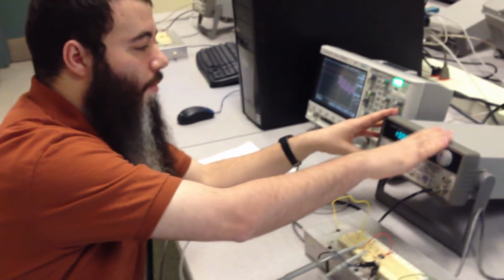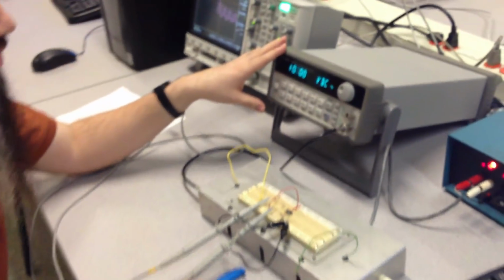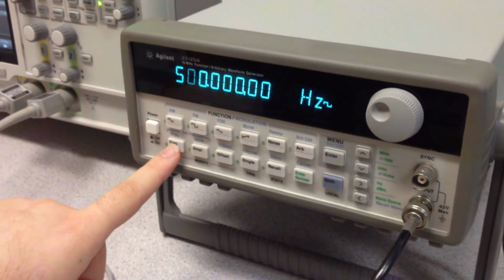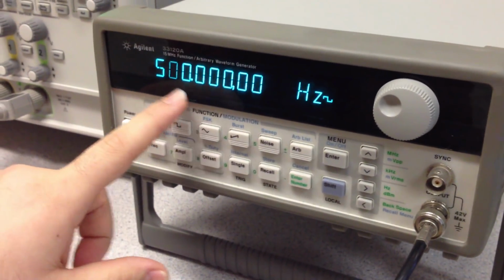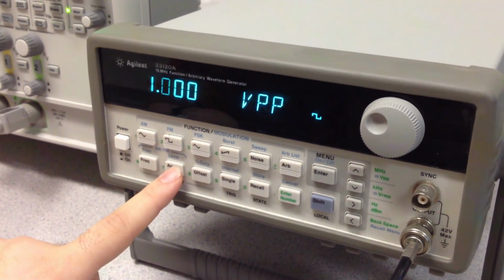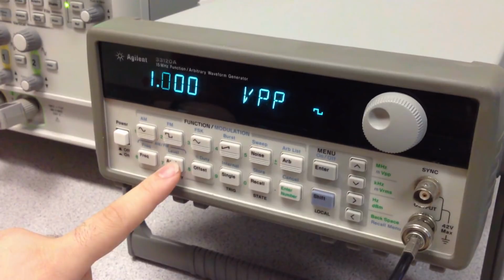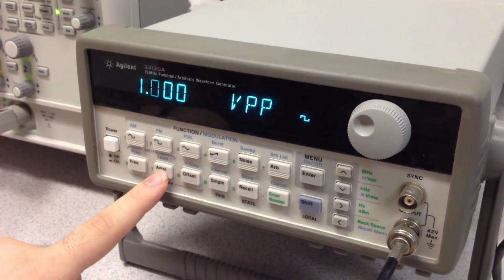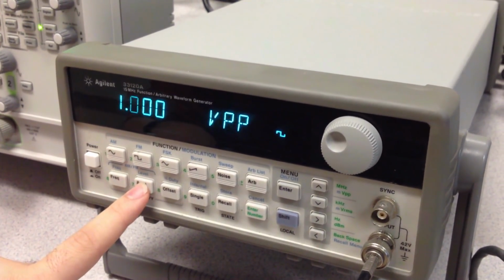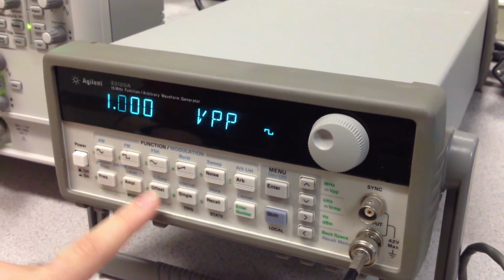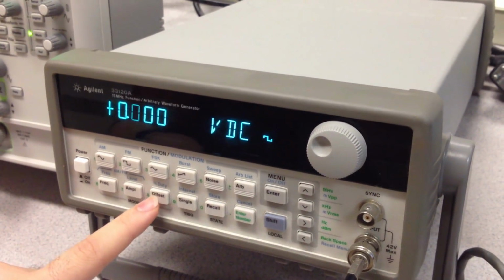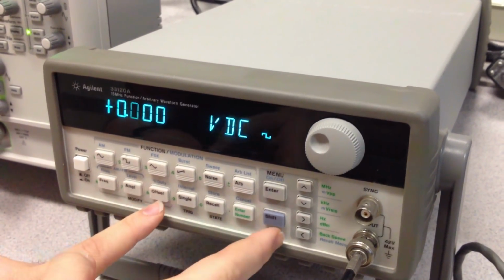We'll try to set this function generator. First of all, this is the frequency. We make sure that it is 500.0 Hertz. Amplitude is arbitrary. As you know, if you scale the amplitude, everything is scaled. I just choose 1 volt peak to peak, but you could make it any value. Offset, I'm not interested in offsets or DC values, I'm interested in the different frequency responses.